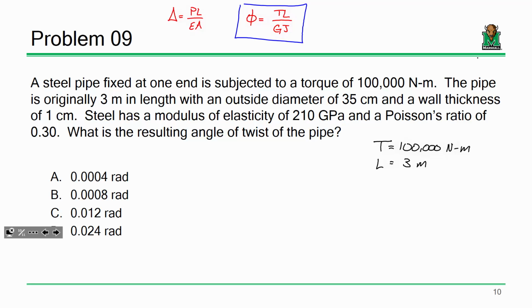Now, let's start off with G. Let's talk about Young's modulus. Young's modulus is a characteristic value for a given material about its axial strain, like steel. Modulus of elasticity of steel is 29,000 KSI if we're dealing in US units.